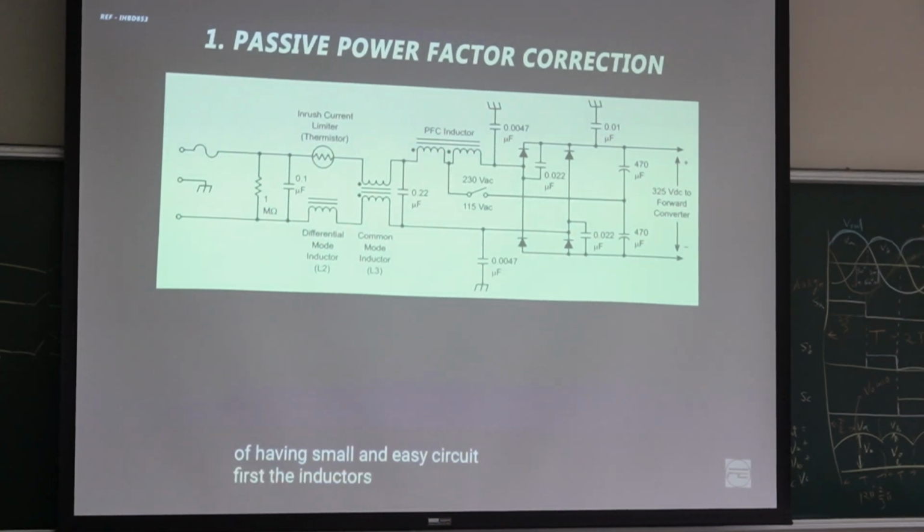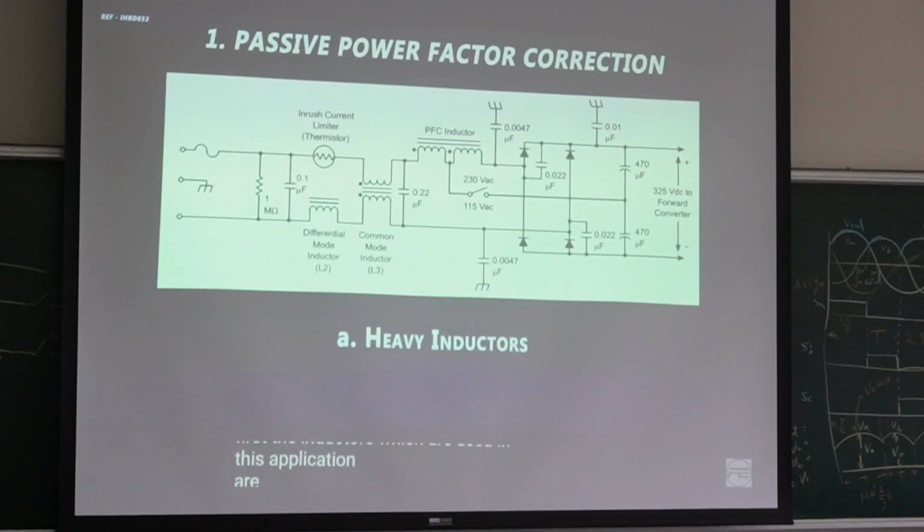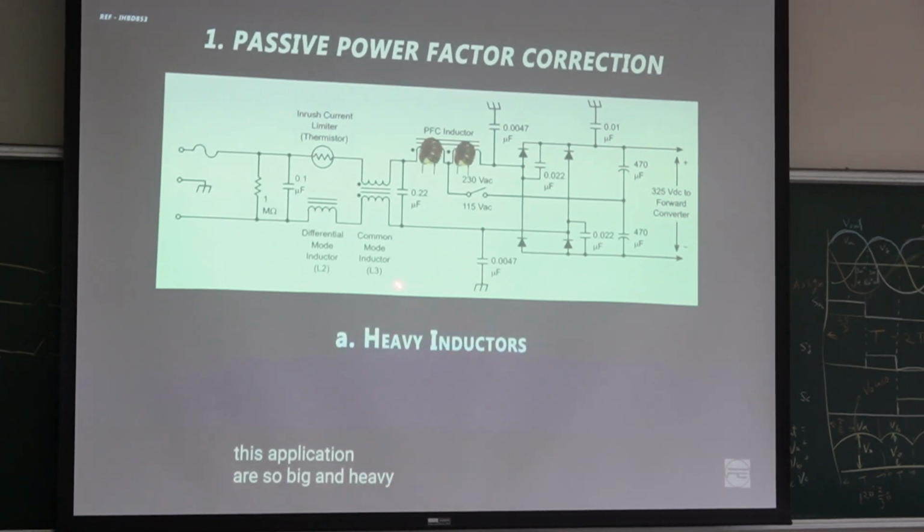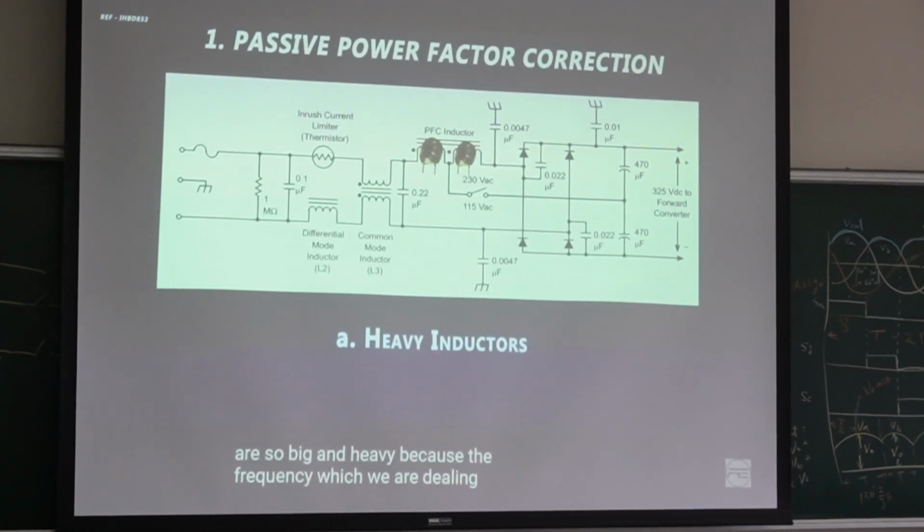First, the inductors used in this application are so big and heavy, because the inductor is frequency dependent, and the frequency we are dealing with here is just a few hertz.